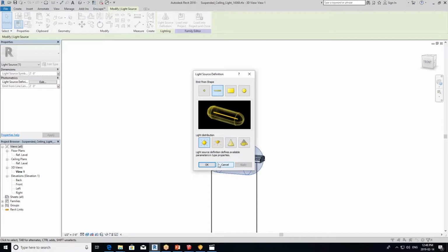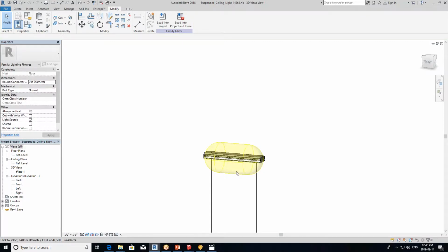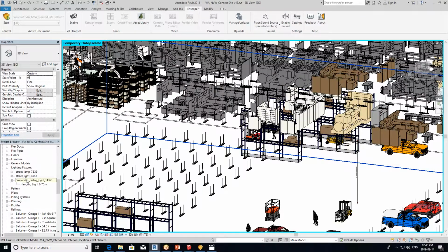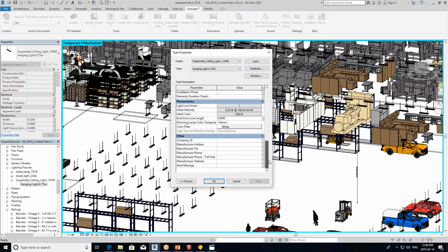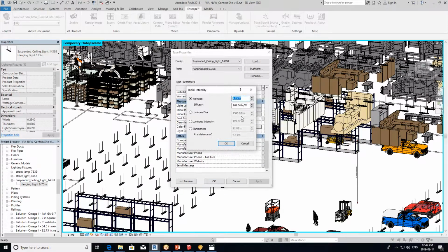I think Lumion has a little bit more customization inside the lighting effect, whereas Enscape is what it is. But if you want to modify how much light you want to put in, you kind of have to do it in here. So in this particular hanging light, you have to change it here: color, intensity, you have to give it a voltage and all that.